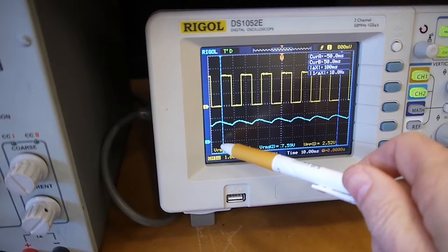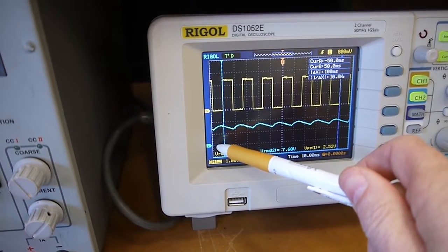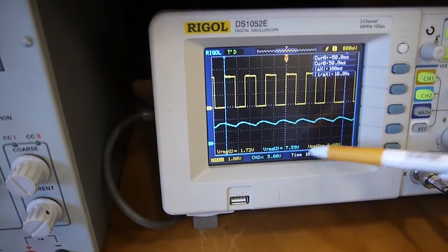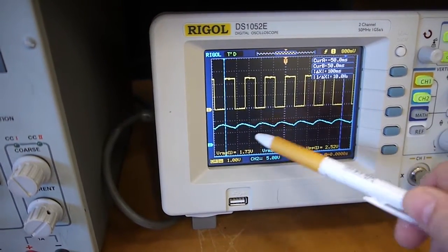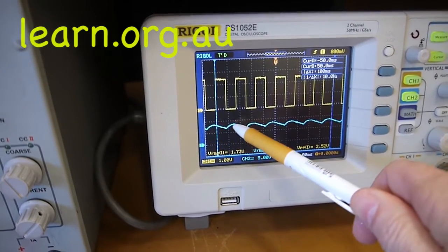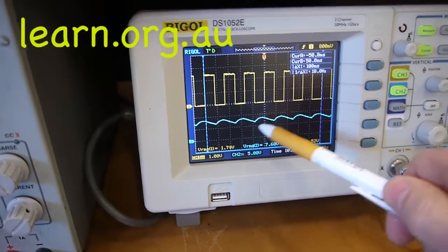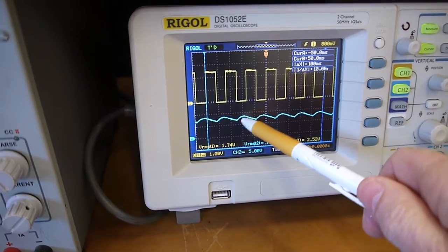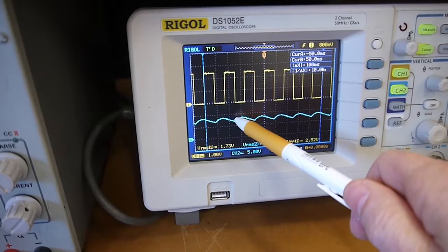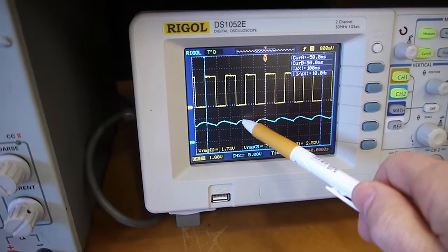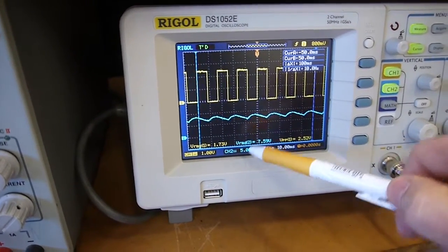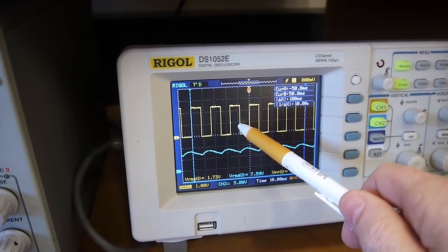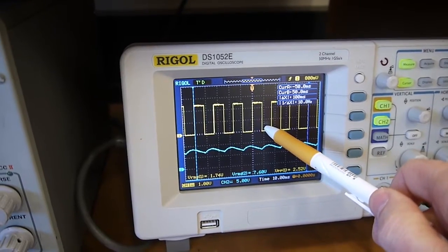Channel 2 on the oscilloscope is also DC coupled, and the 0 baseline is here where the reference marker is, and channel 2 is set for 5 volts per division. You can see the little bit of ripple here on the output of our circuit. I've actually got 5, it looks like about 7.5, maybe 8 volts, because it's going to be somewhere in the average of this ripple value here. Now that's with a mark space ratio or duty cycle of 50% coming in.